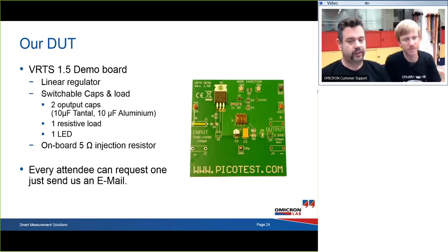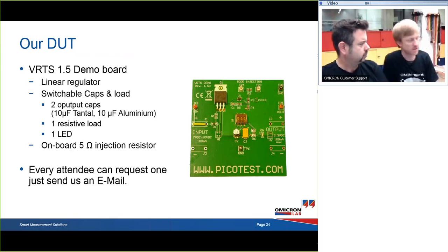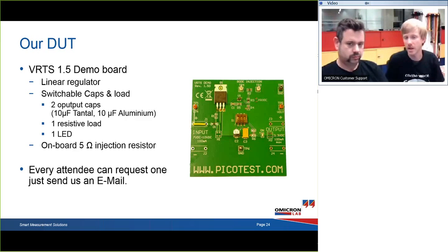We also have a resistive load and an LED. This LED is always connected, so it's a basic load. Florian, how many milliamps does it take roughly? I think it draws roughly 25 milliamps. So if we add our current injector, the PicoTest 2111, then we will have a total load of 50 milliamps if we don't add the load resistor.